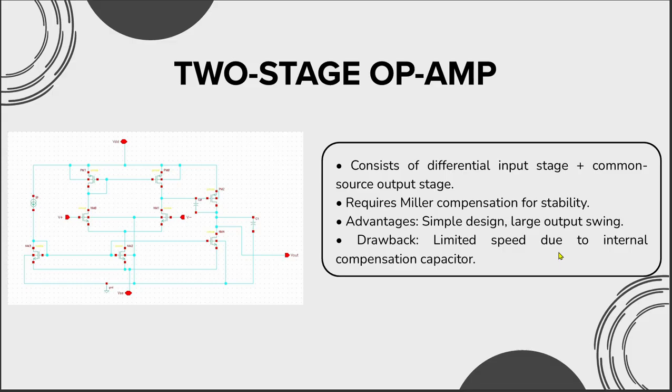This is the two-stage OpAmp topology. It has a differential input stage with a current mirror load and a common source output stage.